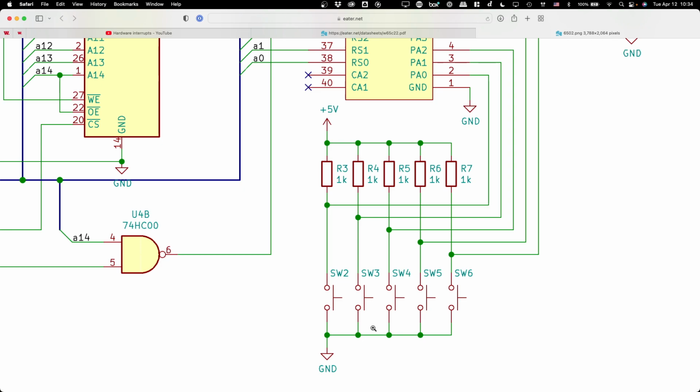We want to be able to have these buttons trigger an interrupt. And what I'm claiming is right now they cannot. Okay, because what are the ways that we can trigger an interrupt on the 6522? We just looked at it. There has to be a level change on CA1, CA2, CB1, CB2, the shift register, or the 2 timers. Okay? Are these buttons going to do any of those things as currently diagrammed in this schematic? No, they will not. Okay?